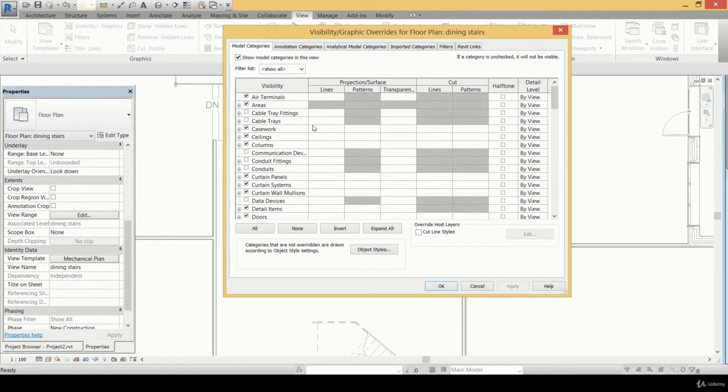So what we want to say is that if you need to activate some options or some controlling tabs for your ceiling or for any floor or for any plan that you are working on, you easily go to the view template and then deselect those options that you need to activate. And now our aim from the visibility graphics is to hide anything that is not related to our HVAC system.